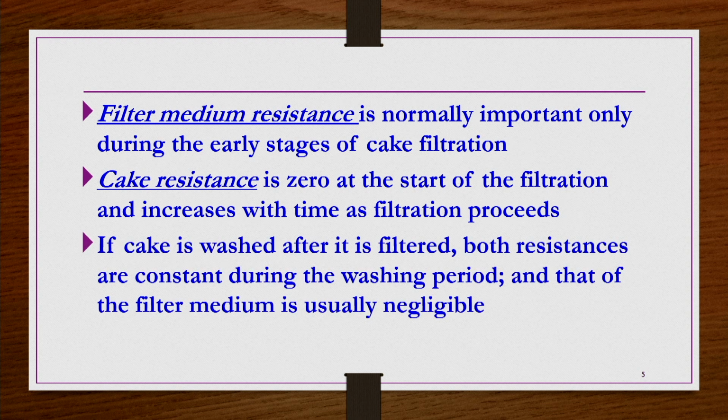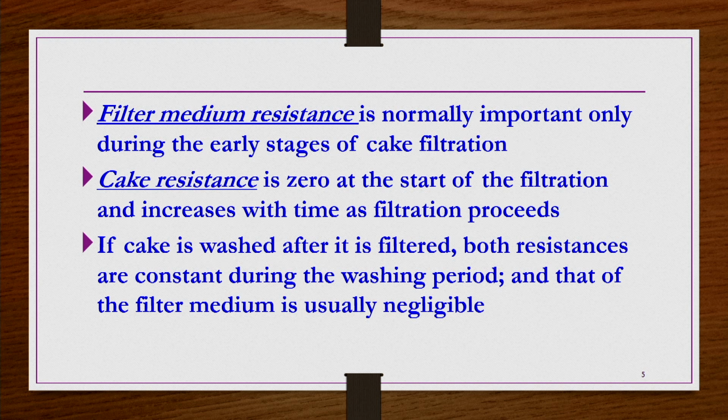If the cake is washed after it is filtered, both resistances are constant during the washing period in general, and that of the filter medium is usually negligible compared to the resistance due to the cake formation. Compared to the cake resistance, the filter medium resistance is in general negligible, especially when the cake is washed after the filtration.